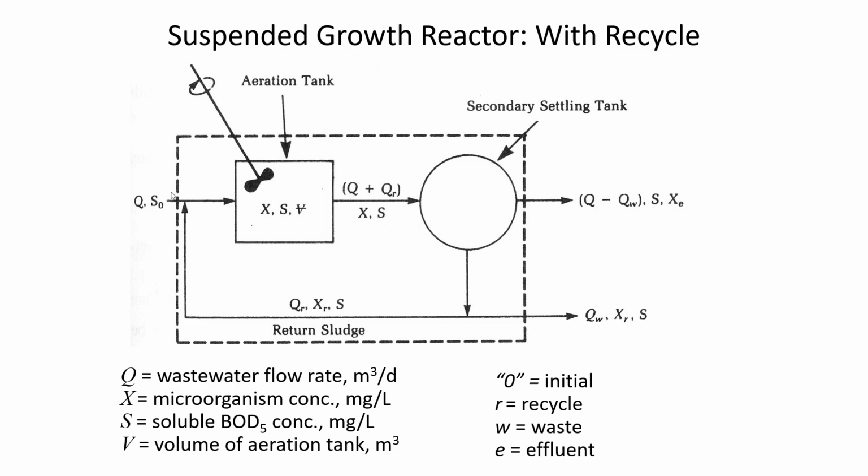So what happens is the microorganisms are reaching into the water and taking food, which is like dissolved BOD, and they're turning it into cellular mass, like their body mass. And so that's what gets settled at the bottom of the clarifier. So this X that's getting wasted includes the broken down components of BOD that otherwise would have been discharged to the river, because the microorganisms are turning, basically you can think of it as sugar water, into body weight.